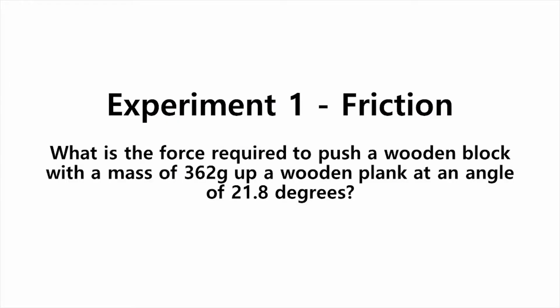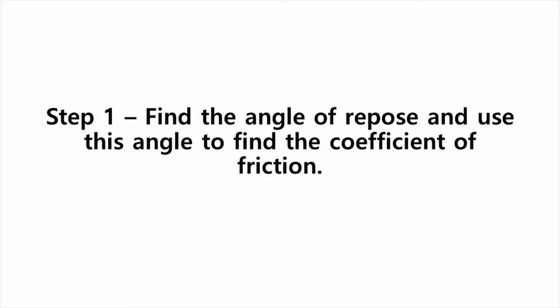For our first experiment, we decided to find the amount of force that is required to push a 362-gram wooden block up a wooden plank which is at an angle of 21.8 degrees. In order to find this force, we first had to find the angle at which the wooden block begins to slide.